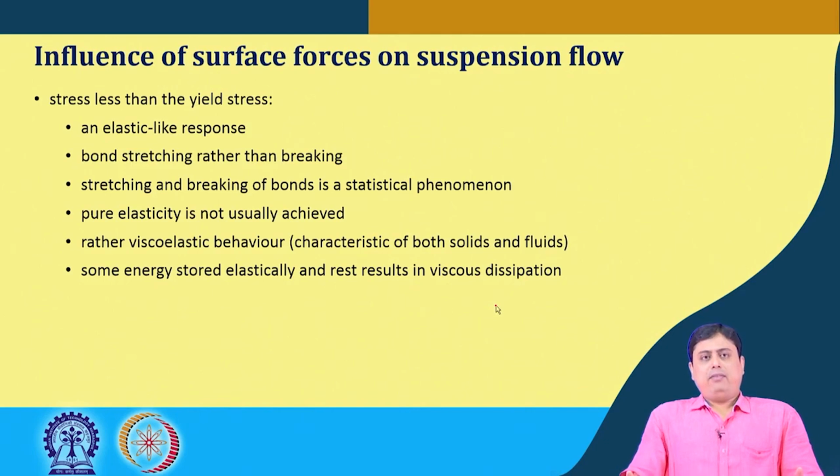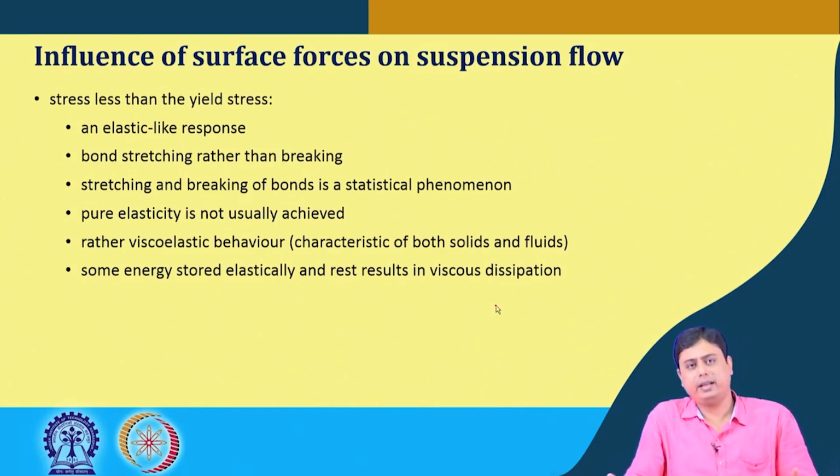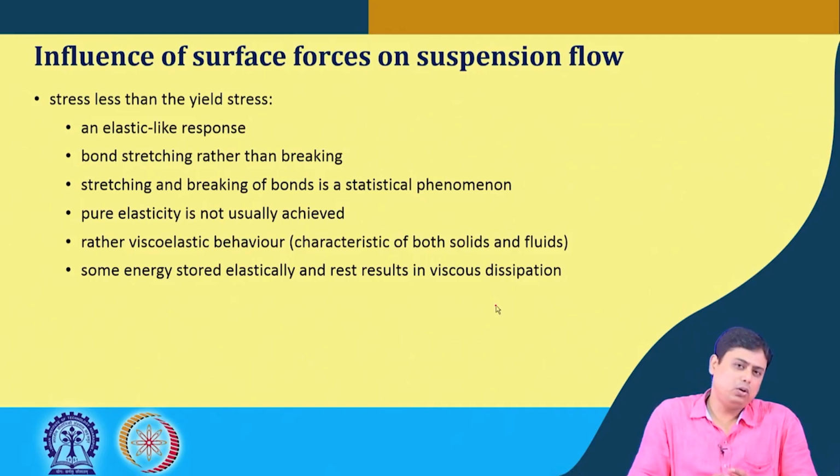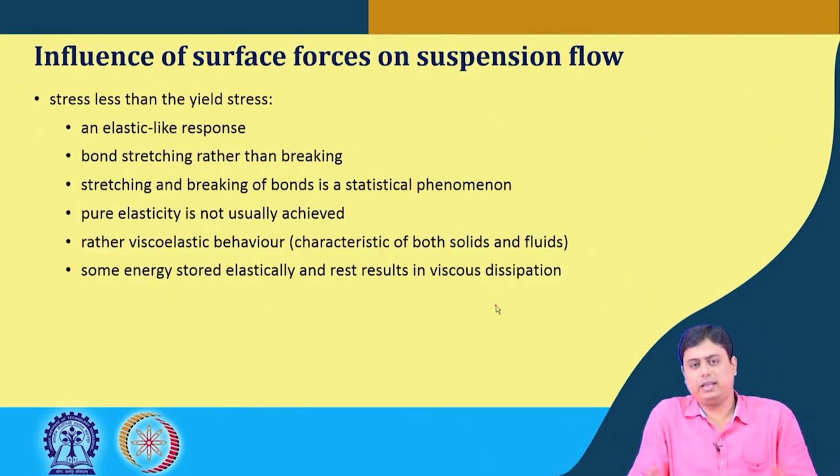So, when we have stress less than the yield stress, it would behave as an elastic-like response, where the bond stretches rather than breaks. Now, this stretching and breaking is basically a statistical phenomenon. So, it would not be a purely elastic behavior as one would have expected for a suspension with fine particles.